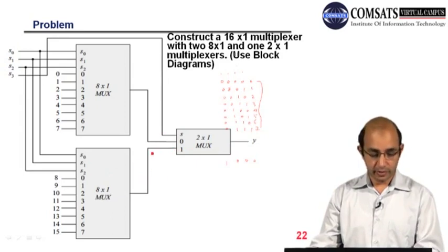So we have constructed a 16 into 1 multiplexer, and we have used 3 multiplexers: two 8 into 1, and one 2 into 1 multiplexer.